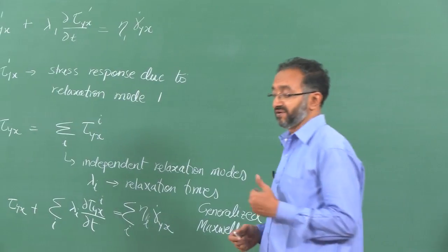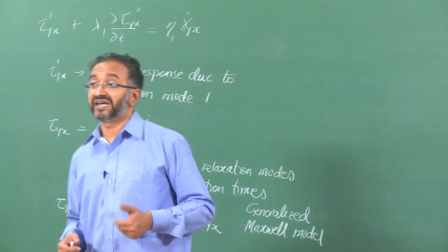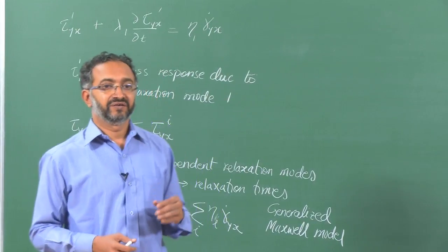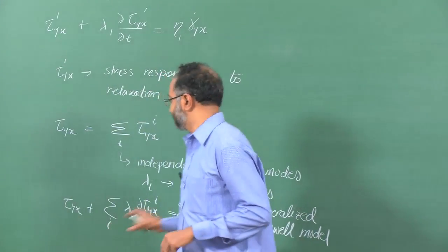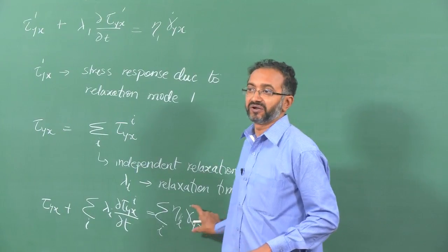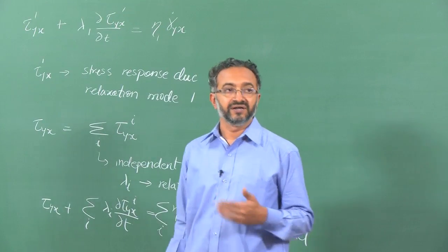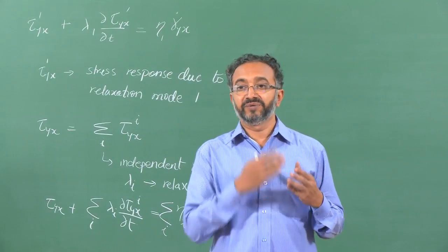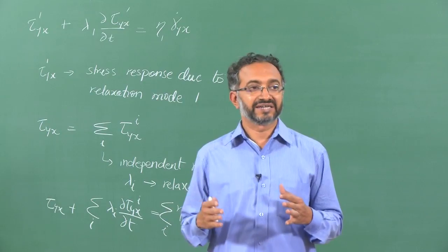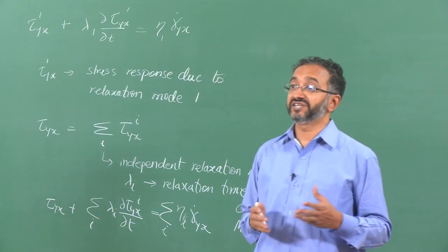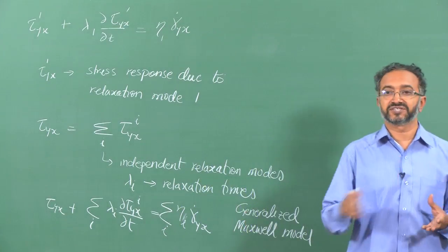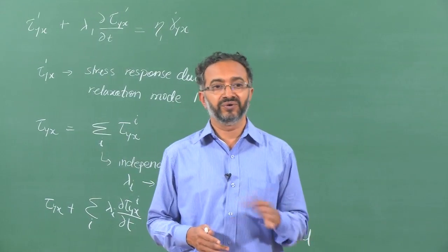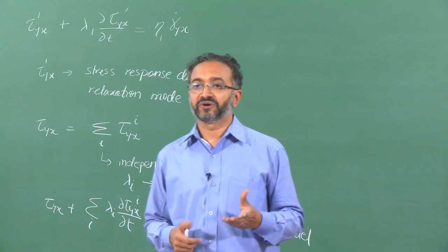So, if you have a material which has definite solid like characteristics and a non-viscous terminal response, then we will have to add on something else in addition to the generalized Maxwell model. We will basically need something which can capture the idea that there will be a non-zero stress relaxation, or the material can retain stress for an infinite amount of time in a stress relaxation experiment, or in case of frequencies, no matter how low you go, the viscous response will not be observed.